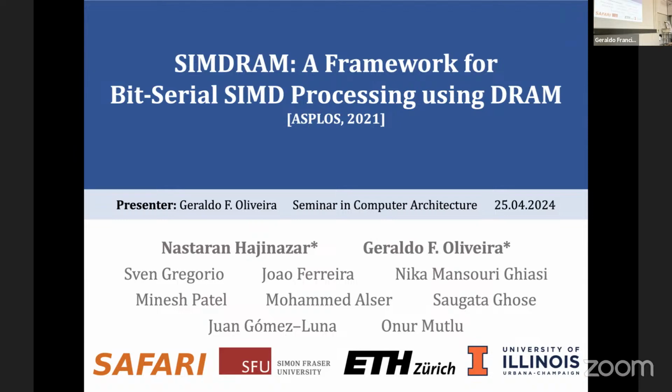So in the ISA, the BBO operation, what information is in one such instruction? The input. There are 3 types of them, so I'm going to talk about the common one for arithmetic operations. It's basically, if you have addition, for example, the addresses of the 2 input arrays and the initial address of the output array, the bit precision of that computation, for example if you want to do a 32-bit addition or a 16-bit addition, and also the size of the arrays. So it's basically that information that's encapsulated there.